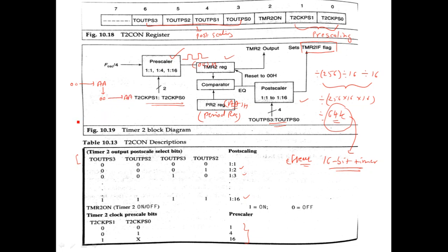So you understand this. This is a sort of auto reload facility. The initial count is automatically reloaded, or in other words, here it's an up counter, so your counting will go up to that initial count, or up to a certain count. In all the previous timer operations, timer 0 or timer 1, the counting will go from 00 to FF. You cannot abort it in between.